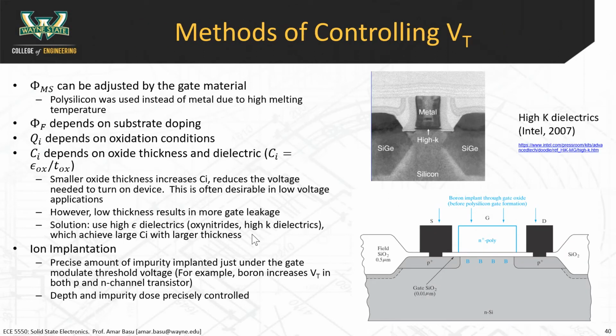I added this slide to talk a little bit about the practical issues of controlling threshold voltages. This gets back to what I was talking about earlier: of all the billions of transistors that we have on the chip, how do we ensure that they have similar threshold voltages, and how can we control the threshold voltages very precisely? All the circuit designers in a chip team are relying on the process engineers to be able to create reliable threshold voltages. Some of you have used SPICE simulations. Circuit designers need to know what that threshold voltage is going to be, whether you're doing digital or analog design.